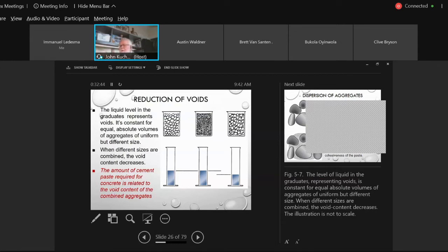If you're using aggregates, say, from the Burns Hill source, where you may have some crush, but most of it may be just natural erosion, subangular, somewhat rounded, and those aggregates are sheared from the test, then you know that the bond was greater than the tensile strength of that aggregate. So that's what you want.